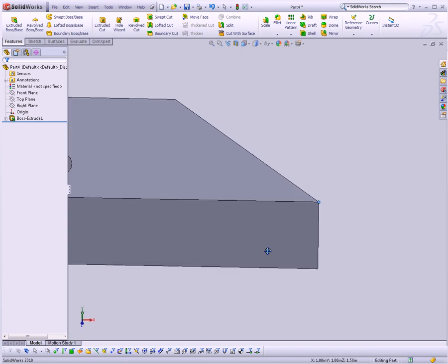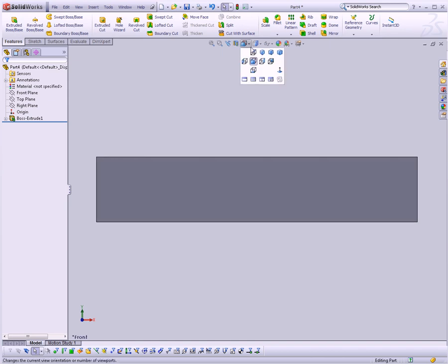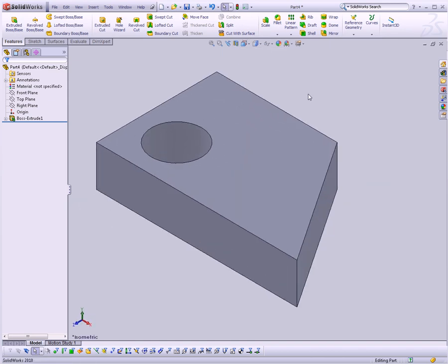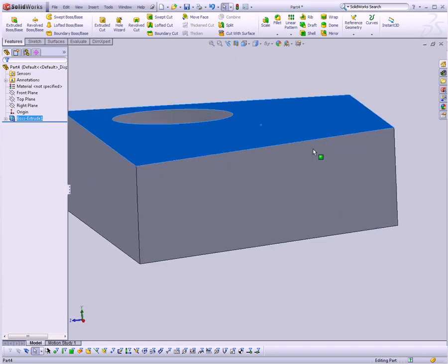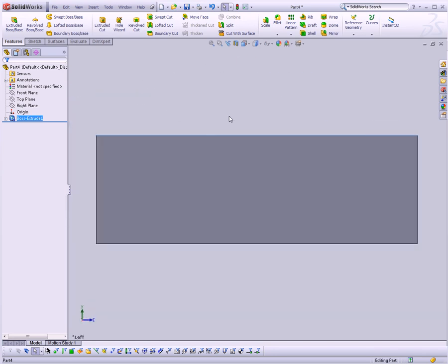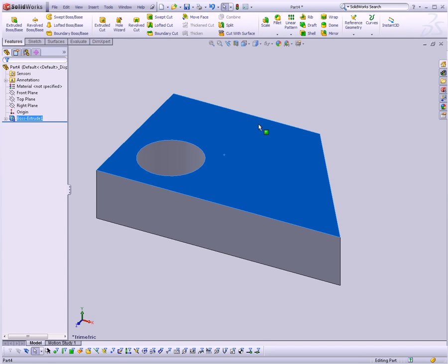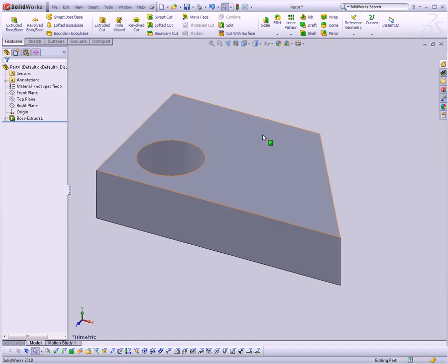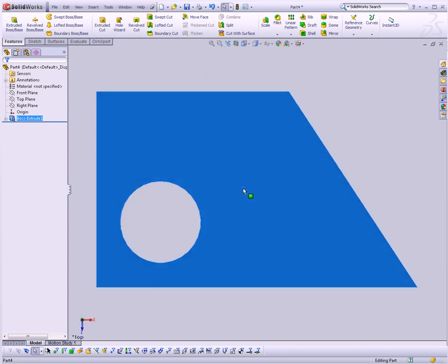Now I can also use these buttons here to change to my orthographic views or to change back to my default perspective view. I can also use mouse gestures, and that's what we were talking about when I said 8 gestures. If I right click in the viewport and drag in any direction, it lets me choose from 8 different default views. So I can choose my right view, for instance. Just drag all the way over, and there we go to our right view, left view, top view, or perspective. So in this case, right-clicking and going up to the diagonal top right takes us back to our kind of home view, which I think is a really handy thing to know about.